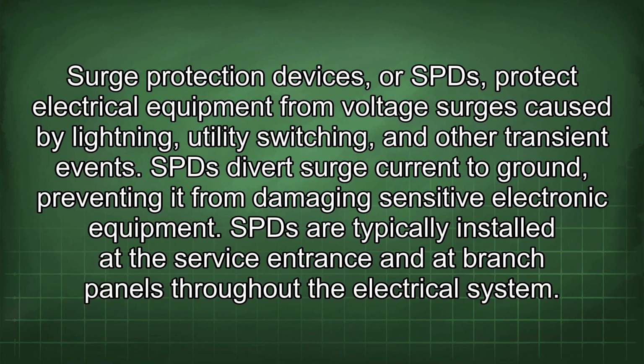Surge protection devices, or SPDs, protect electrical equipment from voltage surges caused by lightning, utility switching, and other transient events. SPDs divert surge current to ground, preventing it from damaging sensitive electronic equipment. SPDs are typically installed at the service entrance and at branch panels throughout the electrical system.